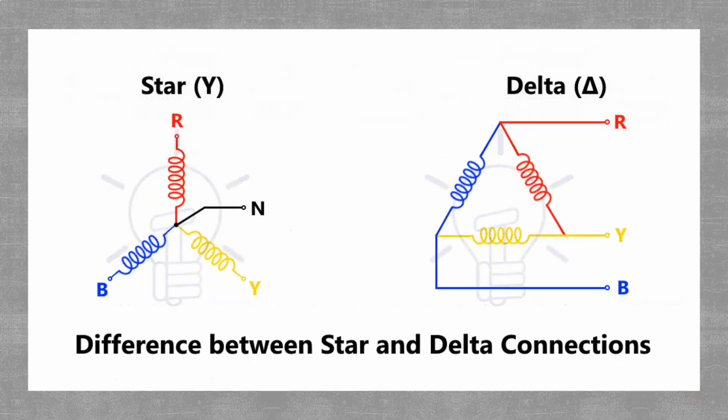So the star on the left is our second bullet point, where it's talking about if the fourth conductor is used as a grounded conductor. You can see this center tap off the Y, that's our neutral. And for a delta, you can't see it on this representation, but what will commonly be done with delta systems, you don't really see them much anymore, they're kind of an older thing. But on one of these windings, whether it be the R, Y or B winding, you'll have a center tap in that winding that'll split it, and you'll come off of that to use as your grounded conductor. If you do that with a delta, then you have to ground the system.